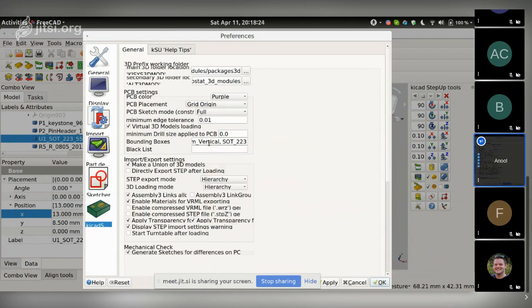it will load only those parts and exclude everything else. So in this case, for today's demo, I've populated this list over here, and it starts with a list command, and then you list all of the step footprints that you want loaded. So right now it's just a couple of them. Let me see. Go back. There's the 9-volt battery clip. That's the Keystone part number 968. There's a 0805 LED. There's a 2-pin header, 1x02 vertical, and the voltage regulator, which is a SOT223 package.